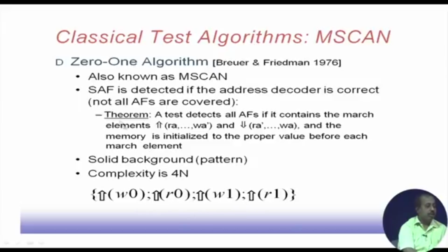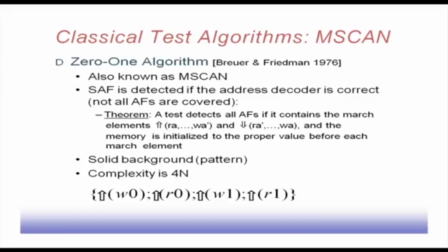If the address decoder has some problem, then of course some other location may get selected. So, you cannot be sure whether it is a stuck-at fault or an address decoder fault, but assuming that the address decoder is okay, we can detect all the stuck-at faults.